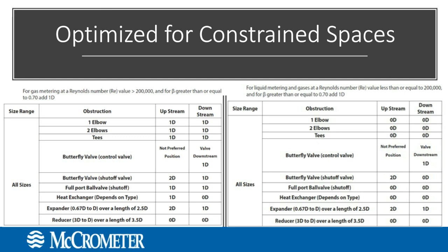The only one that we have a little bit of concern with is if it's placed directly downstream of a control valve. Shut-off valves, we don't have the same problem with, but the partially open gates on the valves can create some problems for a number of different flow measurement devices.